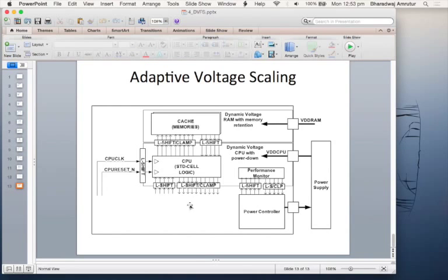That is what is called adaptive voltage scaling, and that is done by adding an additional hardware monitor called the performance monitor. What is that performance monitor, and how do you design it? We'll take it up in the next lecture. But really, that helps the system know, if I want a desired frequency, what the voltage should be, and then the system sets it to that voltage. So I can get additional power savings beyond just DVFS. We'll look at this in the next class.